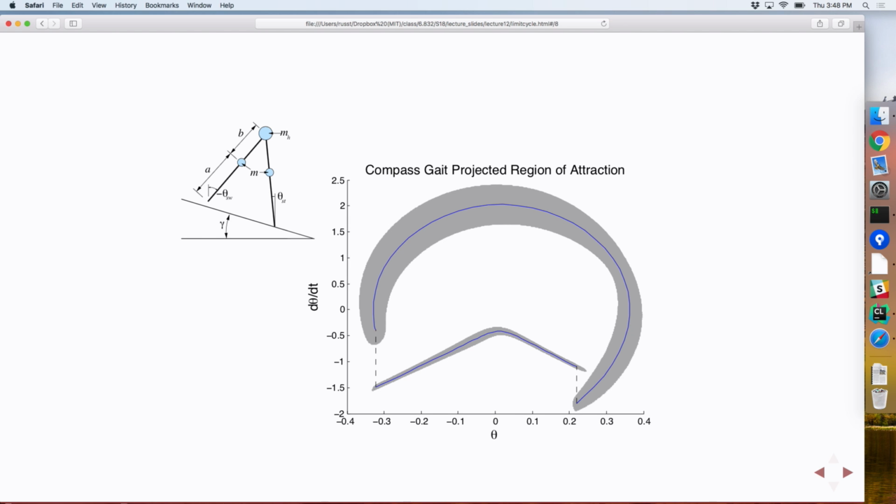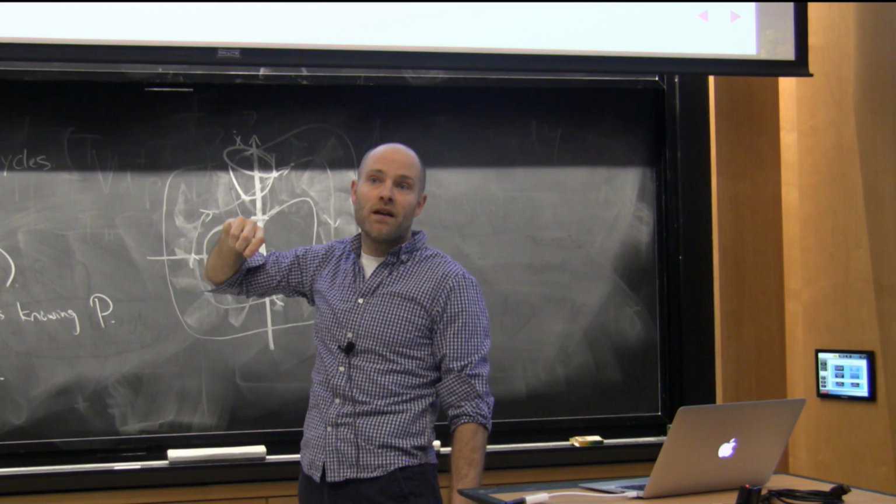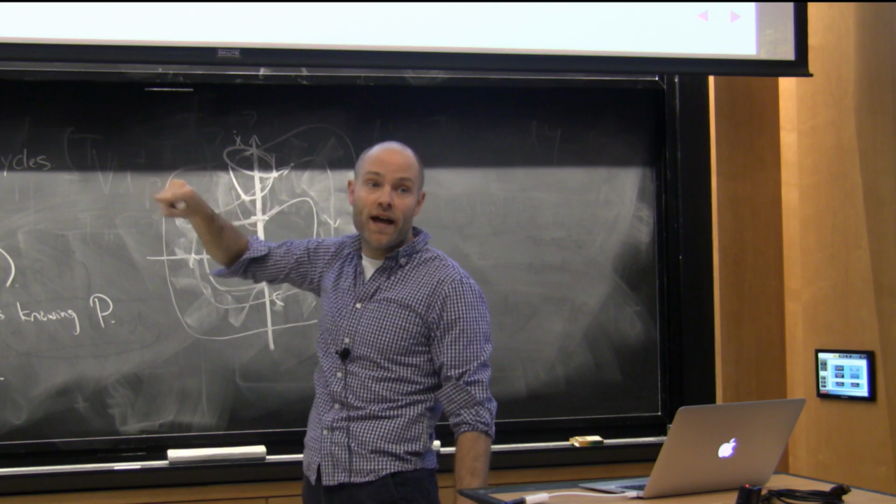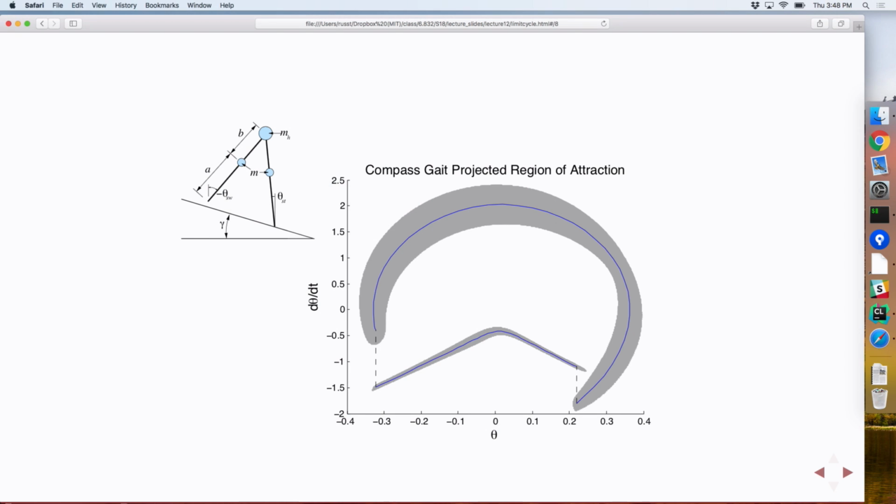And then you could ask, what is the region of attraction of the compass gait? We cannot integrate those equations over time, but we can come up with a Lyapunov candidate that moves along the trajectory, and we can verify that with sums of squares. We still have to know the reset map, and we project the Lyapunov function through the reset map and do its thing.